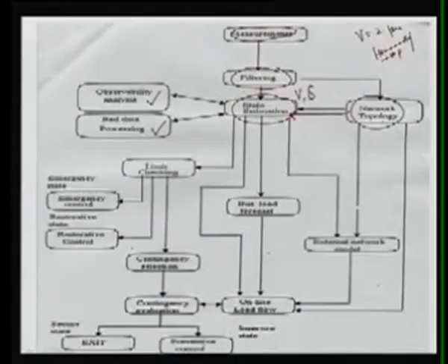So after doing the state estimation, we get a lot of information. First, as I said, we get the voltage and angle, by which we can check the operating limits. Here these are your equality constraints and inequality constraints, which we can also call load constraints or operating constraints.